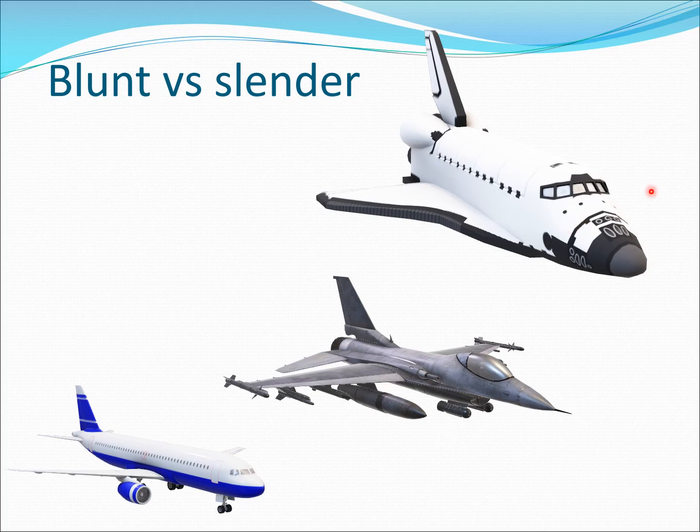Now, if you go to this kind of vehicle which is entering the Earth, you again have a blunt nose, and this blunt nose is even blunter than the nose here. This is a regular aerodynamic shape, but this is as blunt as you can make it. Now this of course is a vehicle which has to go and land on the Earth, so it's relatively less blunt because it's a vehicle which would have multiple design requirements here. This has to fly in the atmosphere and out of the atmosphere. But if you have vehicles which are simply landing, then you will have a really blunt nose of the type I showed in the first few slides.